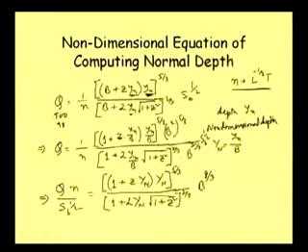Then we need to increase it by a small amount and do the iteration again. But the advantage is that we are already getting a value of yn giving 98 against the actual discharge of 100. Without that approximate value, if we start, we can be very far off from the required discharge, and then we will require a lot of trial and error.